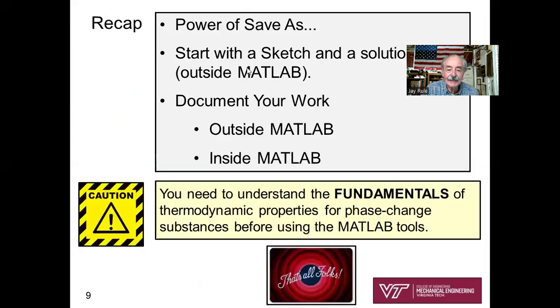Okay, so you get the idea. There is a power of save as. So you can take that original air properties MATLAB file, save as, and start solving problems and utilizing those air property function calls that I'm sharing with you. Of course, it's always important to start with a sketch and plan your solution outside of MATLAB.